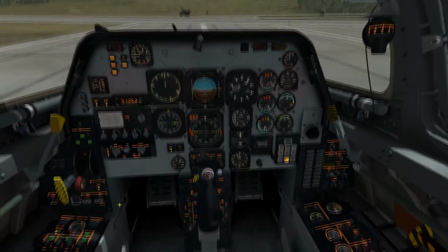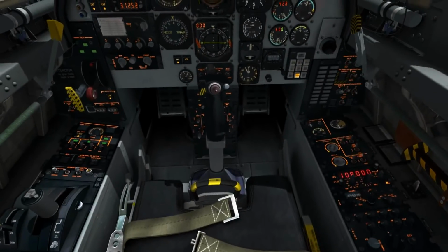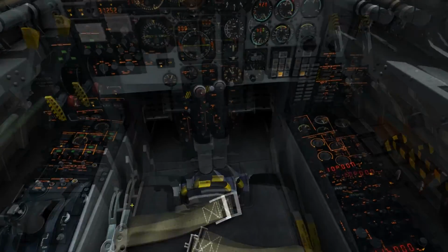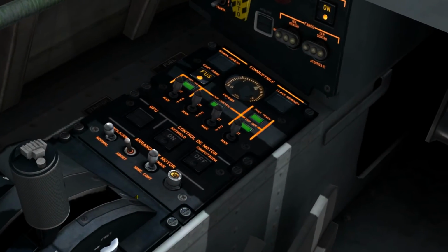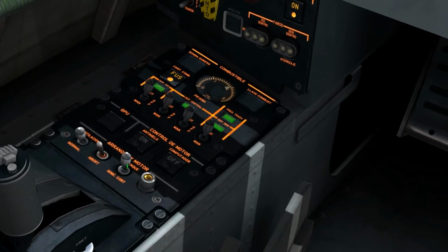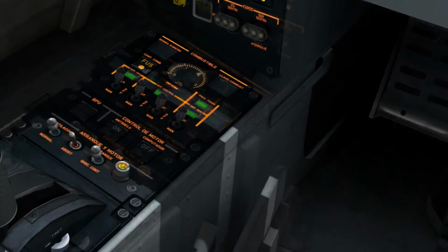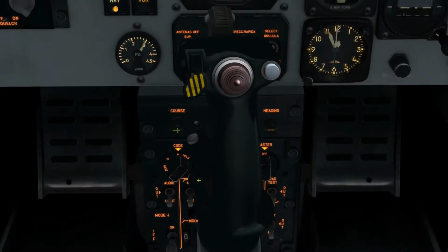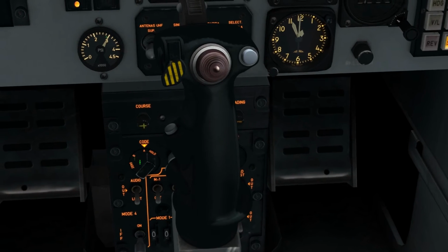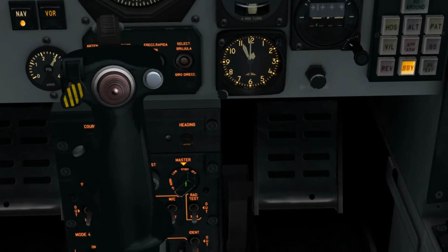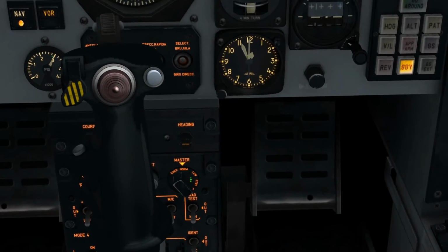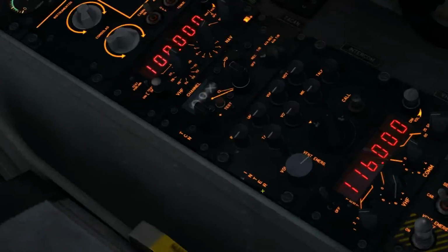Seat clamp, released. Another check for the seat on the rear plane. Ignition mode continuous. It is the same button as the startup one, but the continuous ignition position is this one, and the yellow light is lit up. IFF code, set the code, and the master on normal. Airflow selector, check cabin.